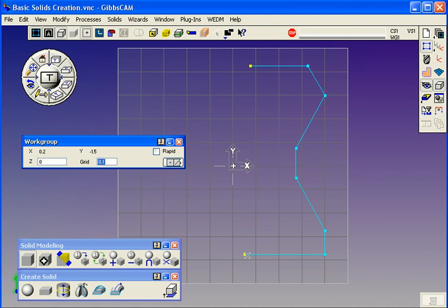Inside the mouse line, also the mouse point tool, when you're through using that tool, just hit the escape key, and that closes the palette and connects the shape into a connected open shape. Notice that both of these end features here are yellow squares, which tell us that's a terminated shape. Terminated, trimmed, for lack of a better word, to themselves at a point. Unlike the blue squares, which are the connections. If you need a review of that, there's a complete set of videos on earlier lessons about the connection aspects and the connection colors that Gibbs uses.